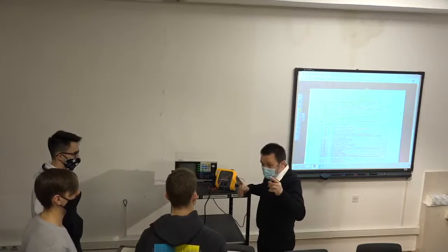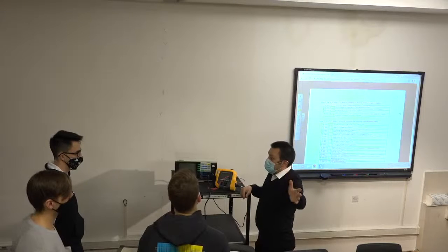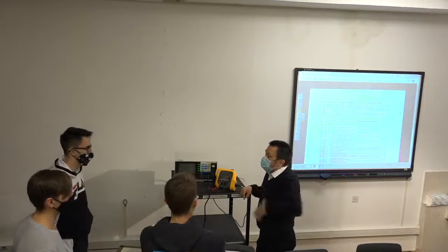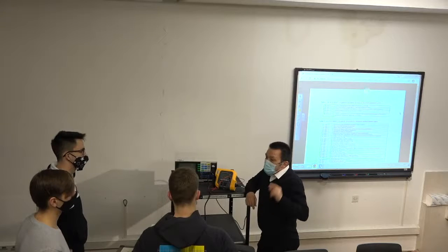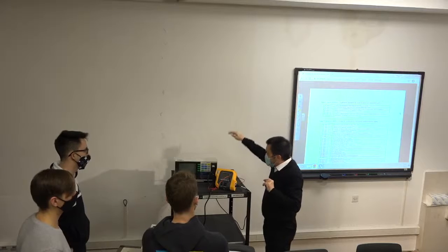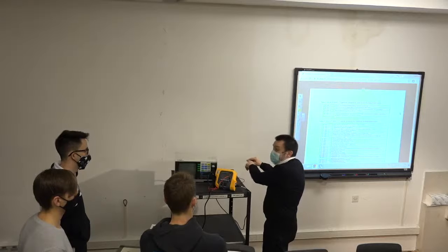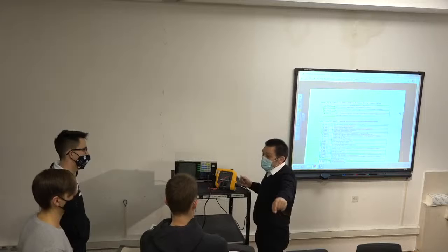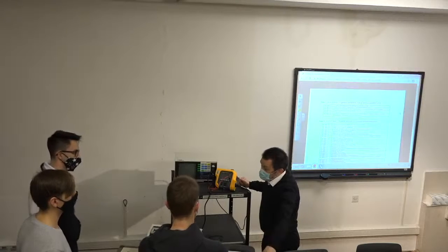Neutral is the line from some transformer that is supplying current for a whole block or something like that. So from there you have line 230 volts to take as much current as you need for your appliances, but the current has to close. So the return current is going to the transformer. And in the transformer, the neutral is grounded.